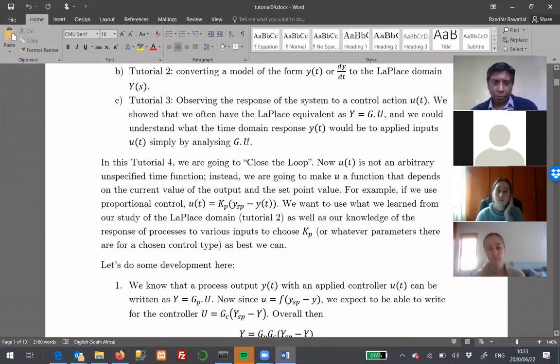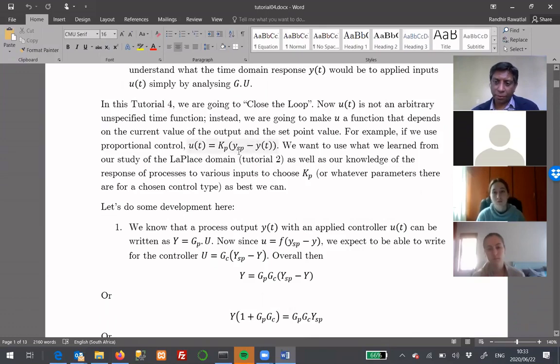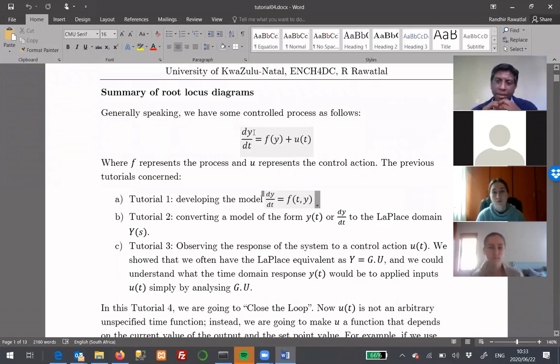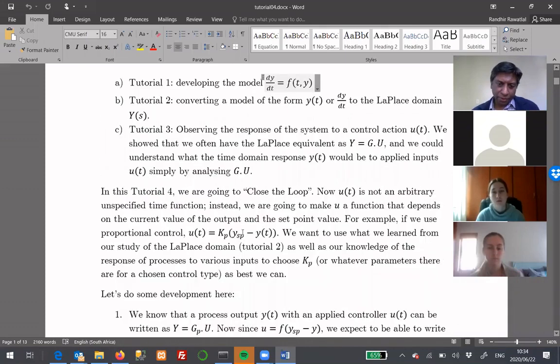So in control, we want to specify some set point for our state. So like we said, y might be a temperature or a concentration. And we know in our process to get this reaction rate in the reactor, we need this temperature and this concentration. So we know what value we want that reactor to reach. So we want to specify some set point value for y. And we'll define that as YSP, Y set point. Yeah, and just be careful of notation collision. I used a subscript S for steady state last time. From now on, SP, that's our set point value.